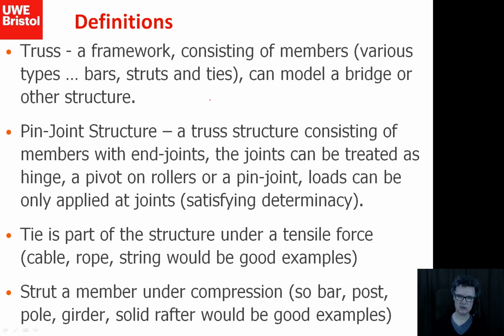So previously a truss structure is something where we've got basically beams all connected together. Typically they're going to probably form triangles in some form. Well, the pin joint is when we're looking at our two members coming together, we're going to put a pin in there. Okay, so that pin in principle can kind of move around at the end of the joint.